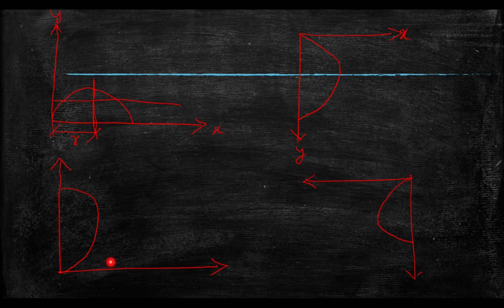And the distance from the base, from the diameter towards the end of the circle, we have the formula 4r by 3 pi. Even if it comes in this direction, this distance is 4r by 3 pi. The remaining thing is r only. Please remember this. You should not get any confusion in this. Starting from the base or from the diameter towards the end of the circle, the formula is 4r by 3 pi. Wherever you can see it, there you can write it as r.